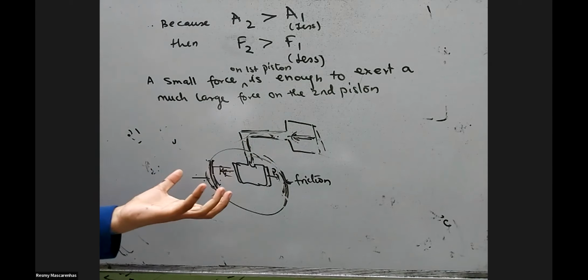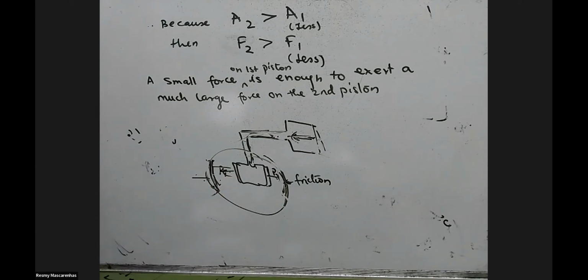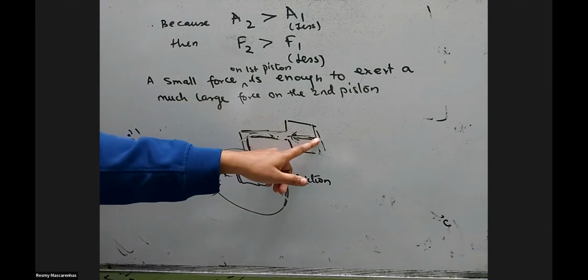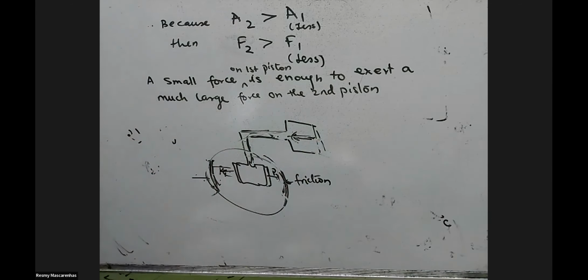Otherwise, if you put extra pressure only on the front and there is no brake applied on the back wheel, there are chances that the bike or car will skid. And the second advantage is that even a small force is enough to create a large pressure in terms of hydraulics.